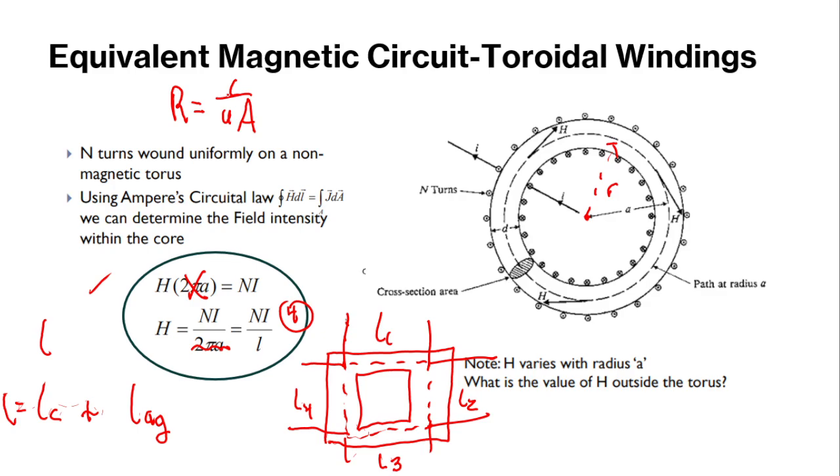So if I have this, how come the reluctance of the air is higher than the reluctance of the core? What value in this makes it so high? Permeability. Why will it be higher in air? Because you use the permeability of free space, not the permeability of the material. So this mu here is going to be a very small value for air.